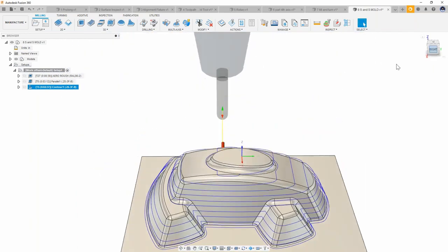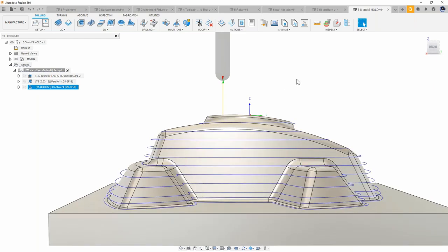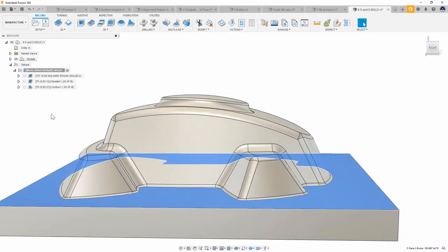If we look at this from the front, though, this kind of operates like a 3D printer, right? Just slicing the model, and wherever the tool would make contact with the model, it is placing a toolpath there. So commonly this is called a contour, but some systems call this waterline, and it's almost like having the part in a container and then filling it up with water. Wherever that line happens to be, that's where the tool would touch it. So that's really how this is generated.